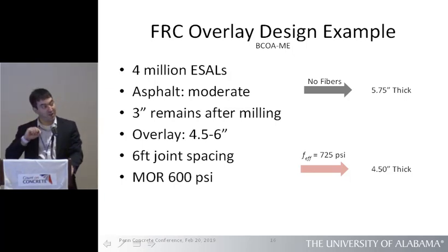Again, it's not telling you how many fibers. You have to run or contract out the lab testing to get these residual strength values for your fiber mix and your concrete mix. But once you have that, you can plug it into any of these design software packages.